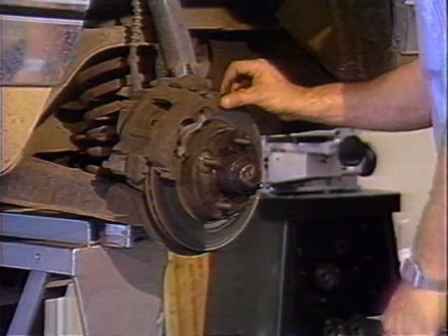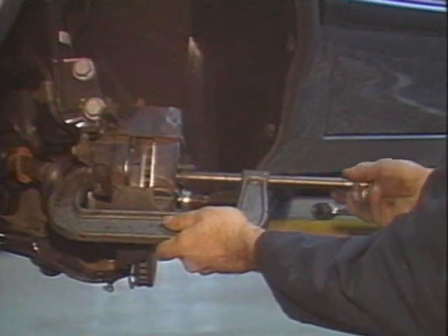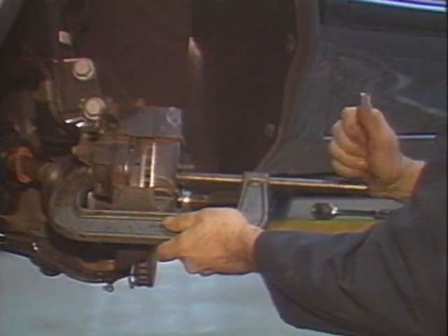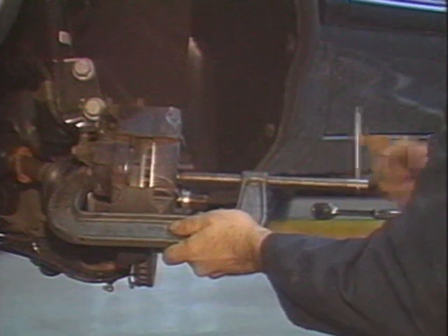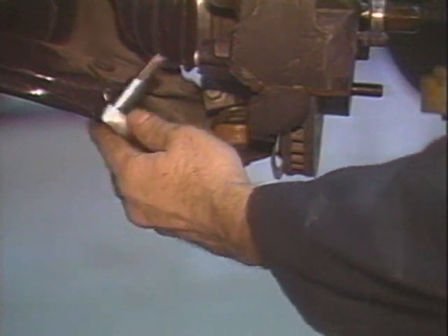When inspecting disc brakes, first check the condition of the rotors. They should not be badly scored, or they would require replacement. Also inspect the caliper for signs of trouble. If the brake pads or other parts need service, begin disassembly by forcing the caliper pistons back into their bores. Use a large C-clamp or even a screwdriver.